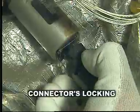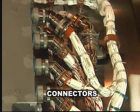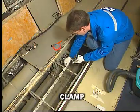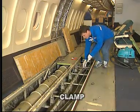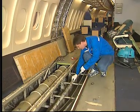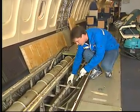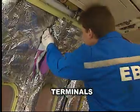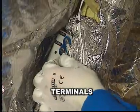Make sure the connectors are correctly locked. Make sure there are no broken parts by applying a light force on the connector. For clamps and supports, make sure the bundle does not move in its attachment by applying a light force on it. Check the terminals are correctly fixed by applying a light force on them.